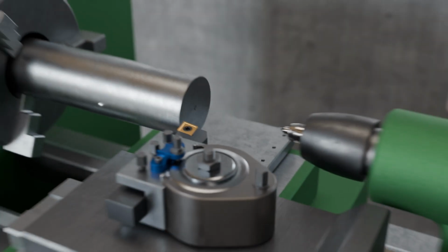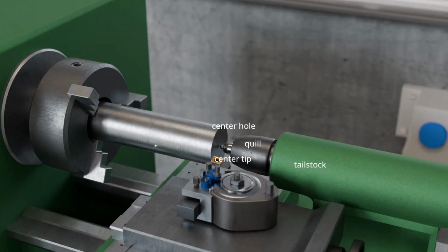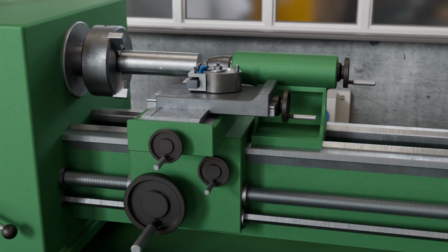During longitudinal turning of relatively long workpieces, which are at least 3 times as long as their diameter, a center tip must be used to avoid vibrations caused by imbalance. For this purpose, the rotating center tip is mounted in the quill of the tailstock, while the workpiece receives the center tip through a center hole. The drive for the rotational movement is provided by electric motors that drive a main spindle, on which the chuck for clamping the workpiece is mounted.